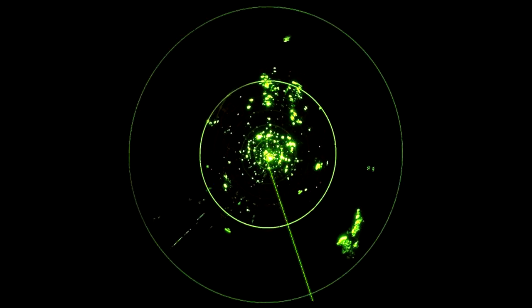Without secondary surveillance radar, aircraft can still be identified by primary radar, but the process is a little more difficult. Remember that primary radar operates using traditional radar principles, transmitting radio pulses, and listening for and timing the reflections. No other secondary data is returned that pertains to the radar target return.